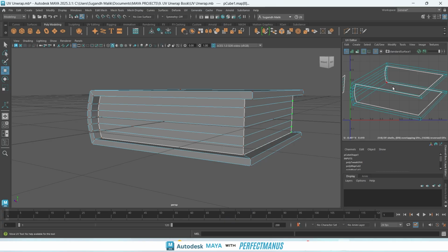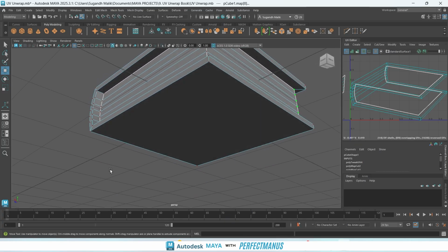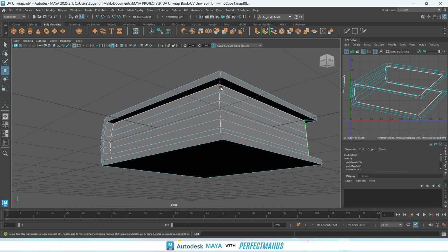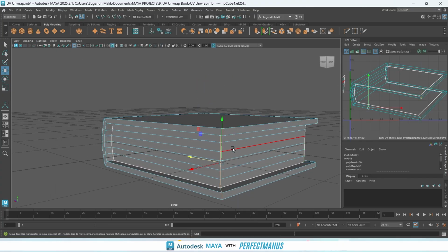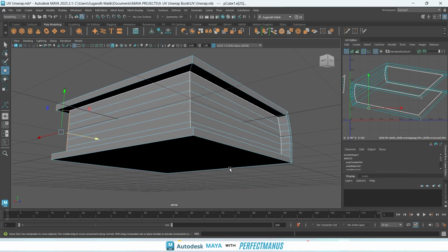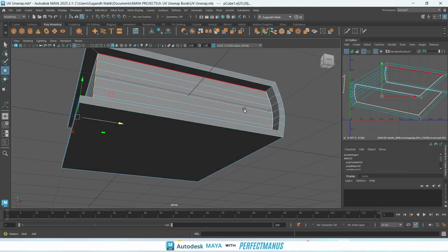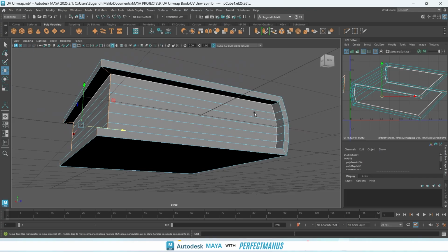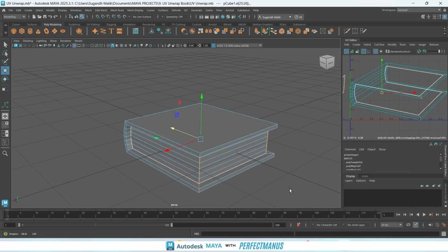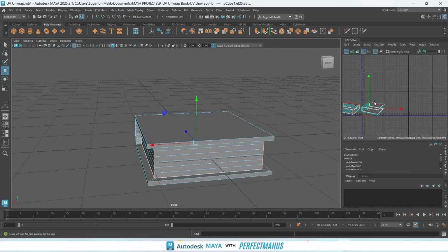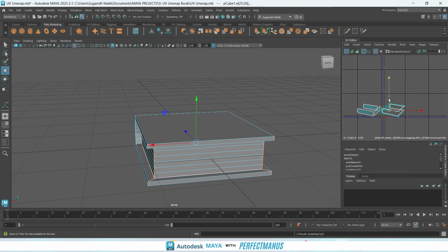Now we need to cut your cover in a way that it can be opened into a single plane. I guess you remember how you put covers on your copy in school. So there should be a cut here because it's folding there till here. Going into the edge mode, you click here, similarly here, and for these parts I'll put those cuts. And I can simply cut it.